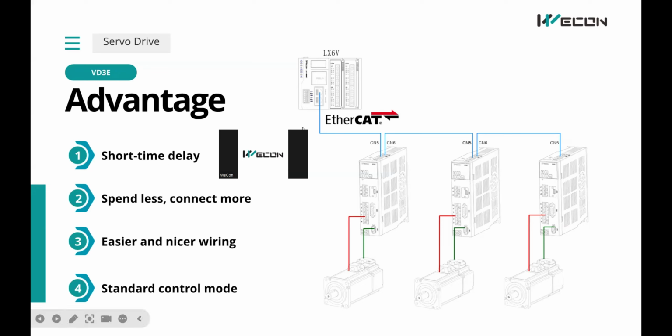So it means, for example, if we set the sync period as 4 ms, our driver will communicate with all our slaves every 4 ms to update the parameters or the control information to our driver.